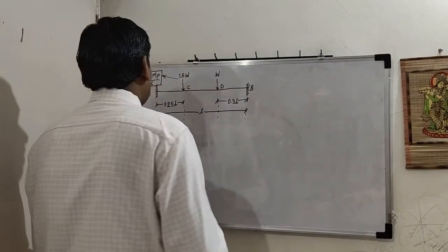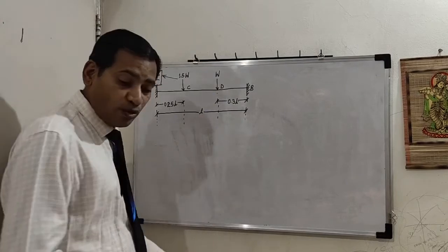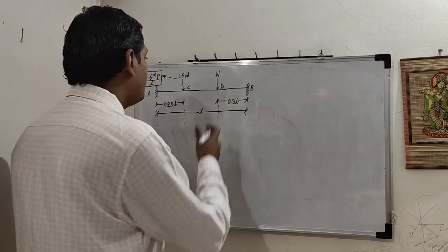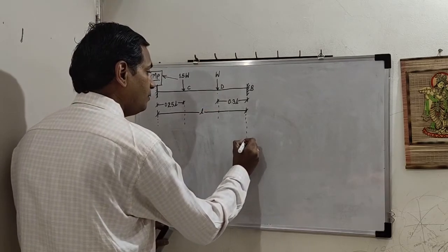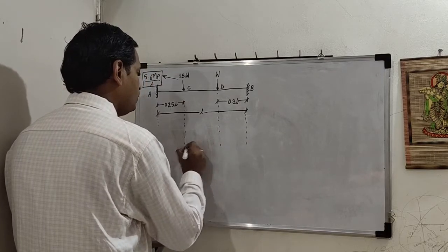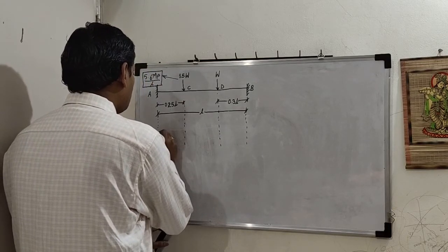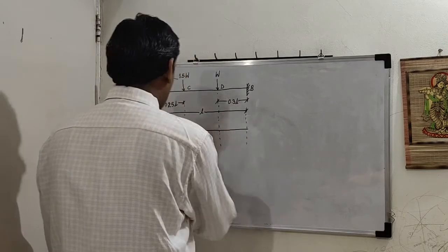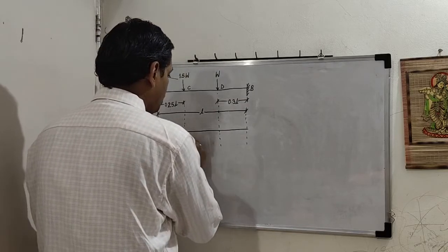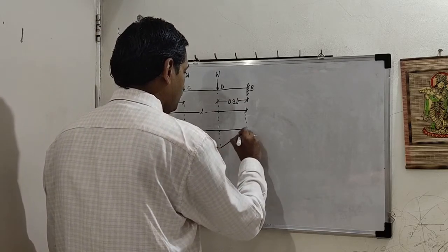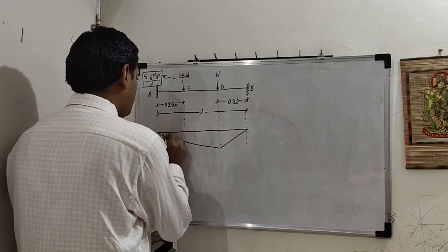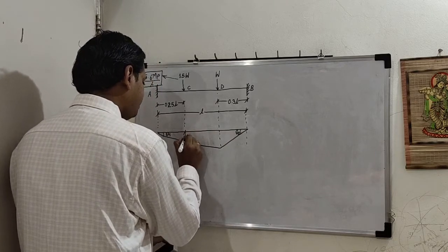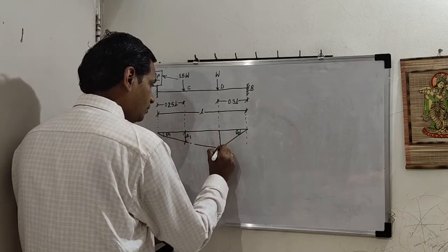Now we shall continue with our next part of the problem. Now we are going to consider the hinge below point D. So now we shall draw the deformed shape. Then we shall show plastic hinge locations, moments, and then we will again complete our usual process, internal work done and external work done. Okay, so this is, we shall again say theta 1, this is theta 2, this is our delta 1, this is delta 2.